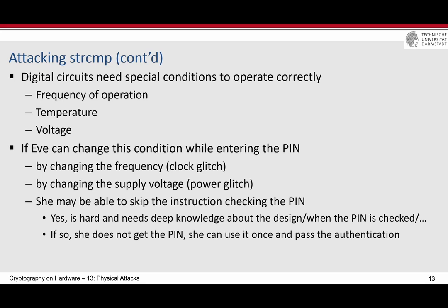For example, you simply run the AES 2 times, and if both of them produce the same result, then you say, hey, this is the ciphertext of the encryption. Of course, then the running time is doubled. Or you have 2 instances of the AES, and you do it at the same time, and then the area is doubled.